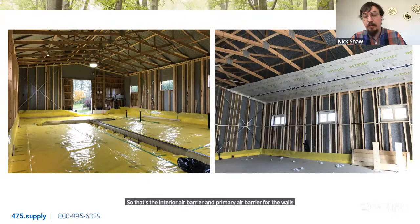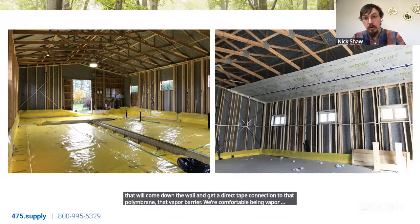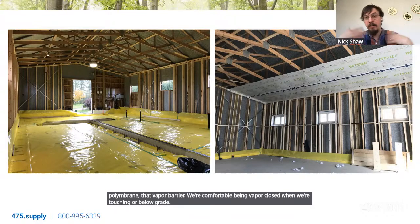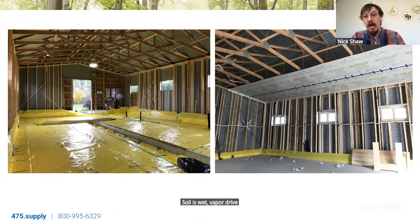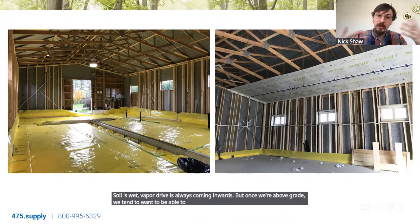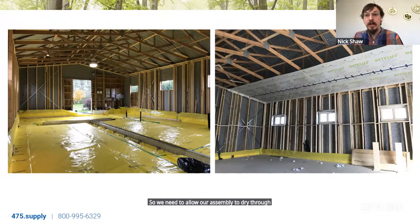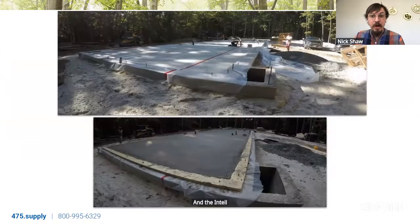So that will come down the wall and get a direct tape connection to that poly membrane, that vapor barrier. We're comfortable being vapor closed when we're touching or below grade. Soil is wet. The vapor drive is always coming inwards. But once we're above grade, we tend to want to be able to dry in both directions. Most of our climate zones now, the vapor drive changes direction based on the season. So we need to allow our assembly to dry through diffusion in either direction. And the Intello is actually vapor variable, so it really helps with that drying process.